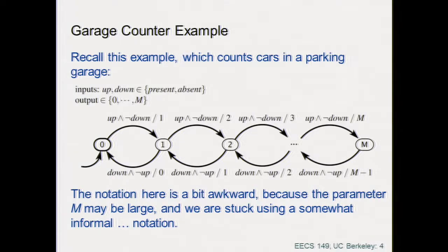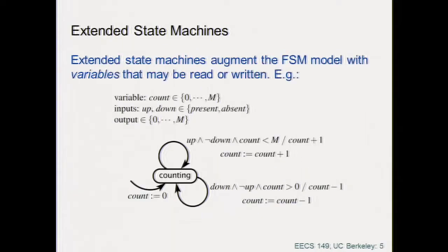Exactly. So what you could do is that this one is essentially a counter, right? It counts up and counts down, right? And so at every transition, you output something, but that is always the same actions. So why don't I reduce all of this just with one state, right? And this one state is characterized by a self loop, which outputs the counter plus one, right? And so this is a way of implementing a counter. It's just a single state. And so that's the way it goes.